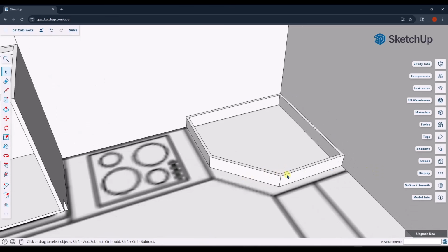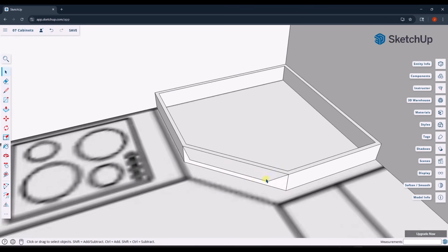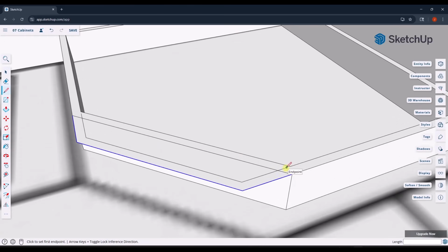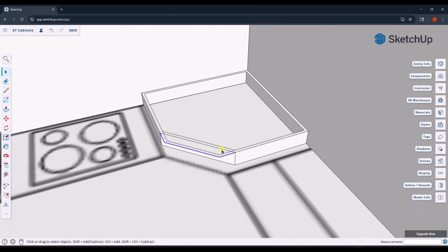And so in order to go to the next step here, all you have to do is just draw a 4-inch edge here and draw a 4-inch edge here. And then you can draw this line across. And then you can select these 3 edges just by doing a shift click. And you can just offset this in by 3/4 of an inch, sorry, right there. And so you can go ahead and complete the edge on either side in order to split these out. And then we're ready to extrude this up.